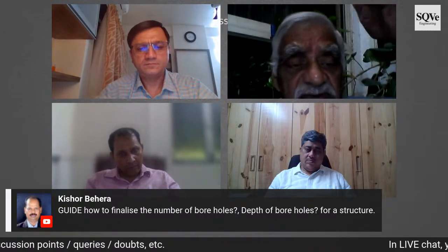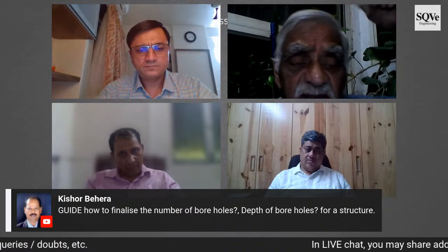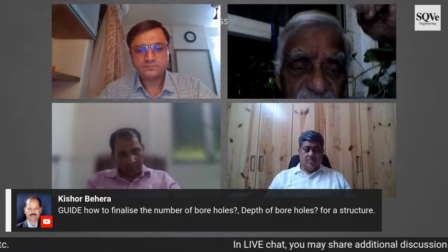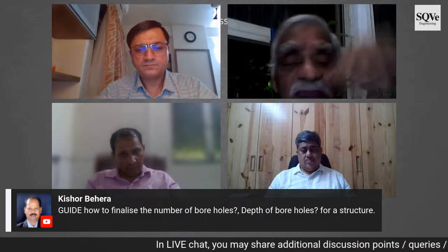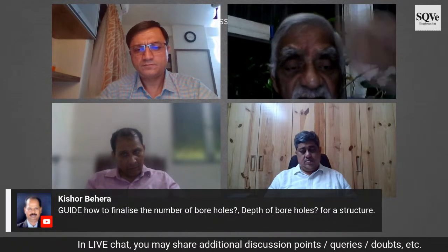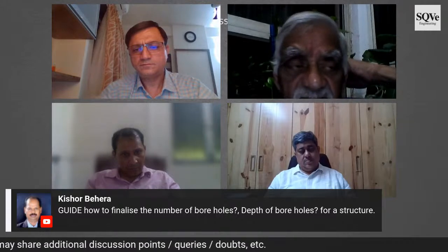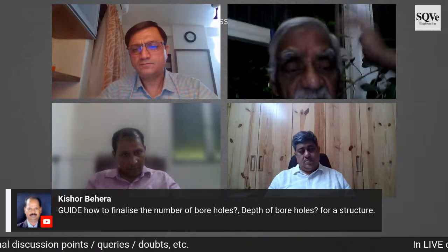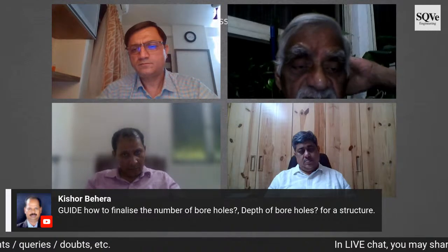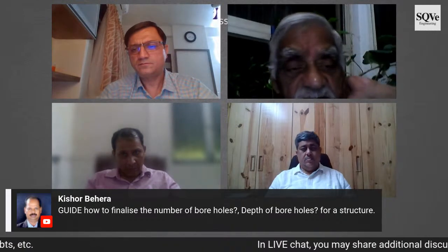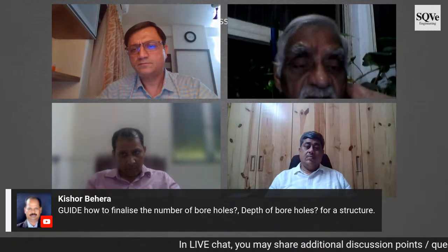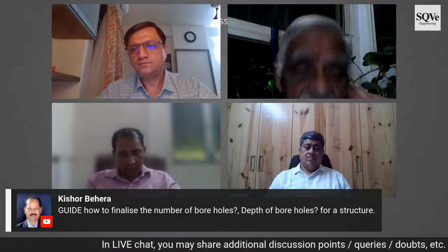We had taken it as 25 30, and the actual bearing capacity came to around 35 ton per square meter. So one way is to make an assumption, go ahead and decide, as Dr. Shukla talked about it. You get a size of the foundation, and minimum 2.5 times the size of the foundation, you'll have to go below and get the bore log to identify.